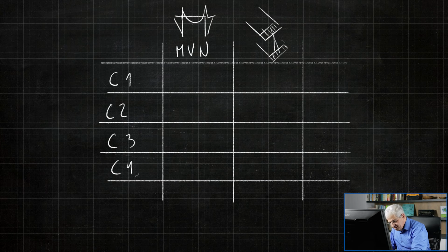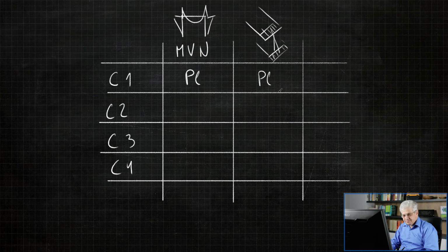So in this case, we have plastic analysis of internal forces and we have plastic checks. If the section is less robust, so that we cannot achieve enough rotational capacity for the plastic hinges, then we need to calculate internal forces with the elastic properties of the cross-section, but we can check the cross-section with plastic properties. This is class 2.